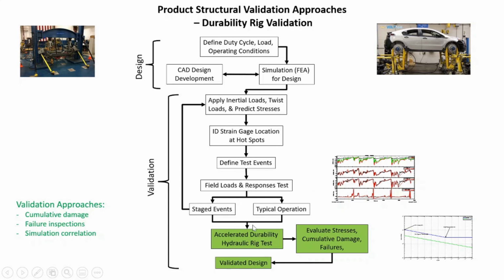How long we actually run the structure on the hydraulic test rig will depend on many factors. The nature of the loadings, the nature of the structure, all will have a big bearing. As the test is being run, we'll be evaluating the stresses, we'll be looking at cumulative damage, and inspecting the unit to see if any failures are occurring.